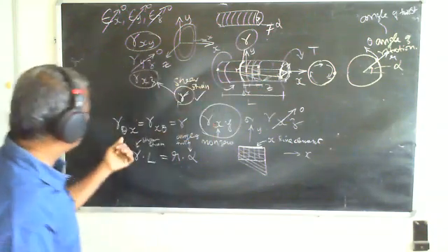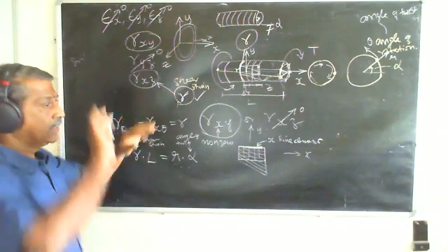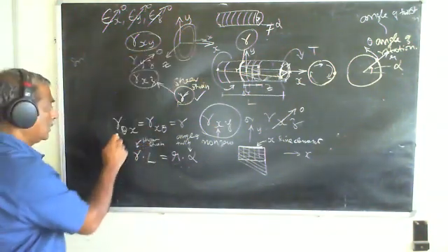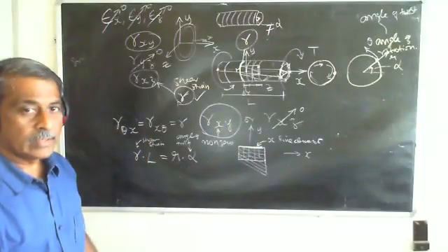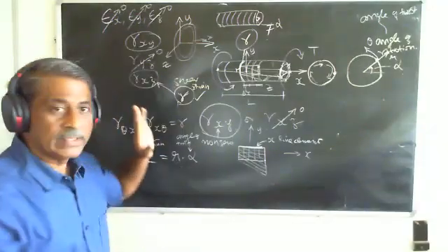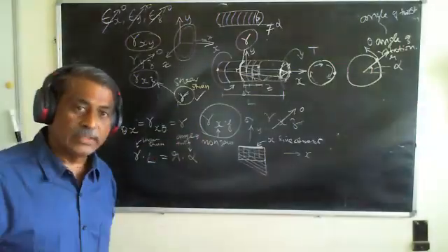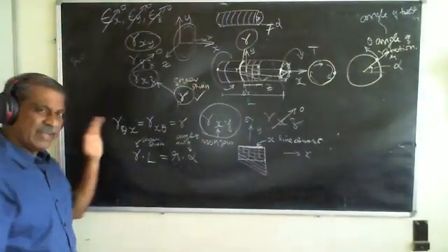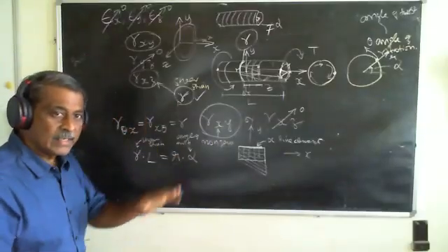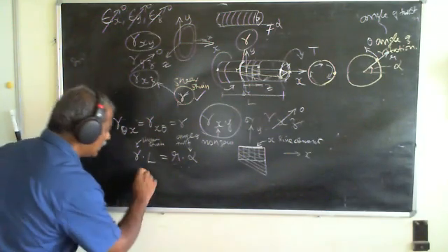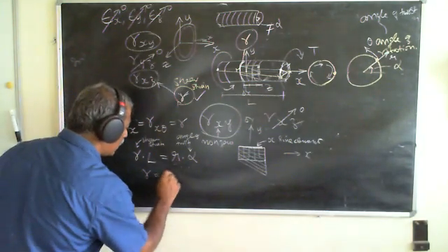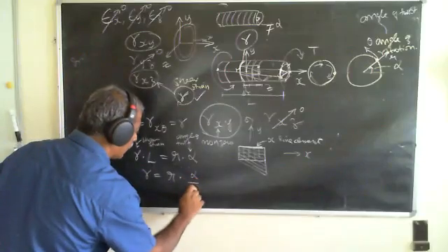To make it more clear, if I take theta as the direction, then it is gamma theta x or gamma x theta which should be present, and all the other strains should be zero, right? So it's a very simple case of one single strain appearing because of twisting. I can also write this to be R times alpha by L.